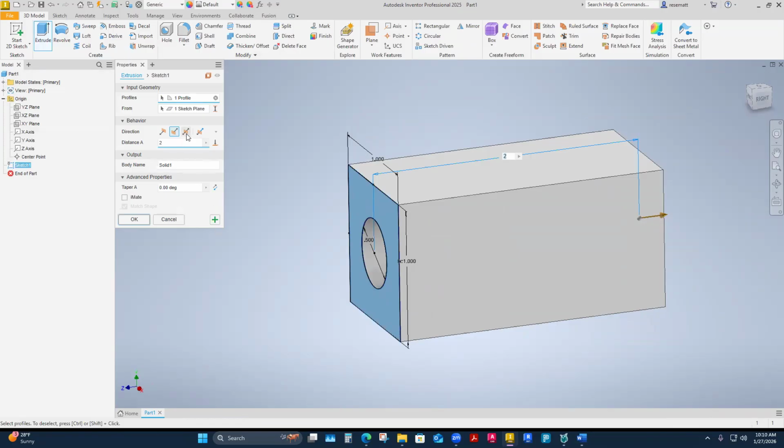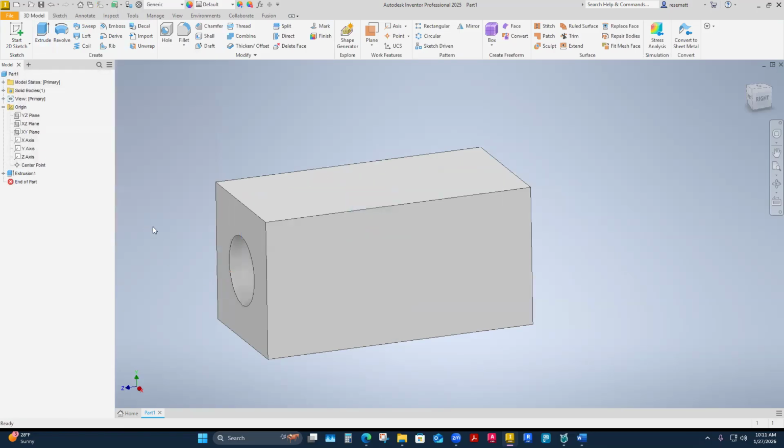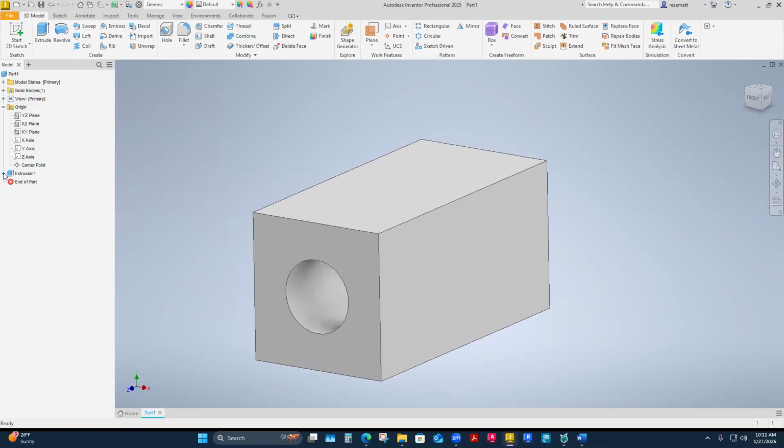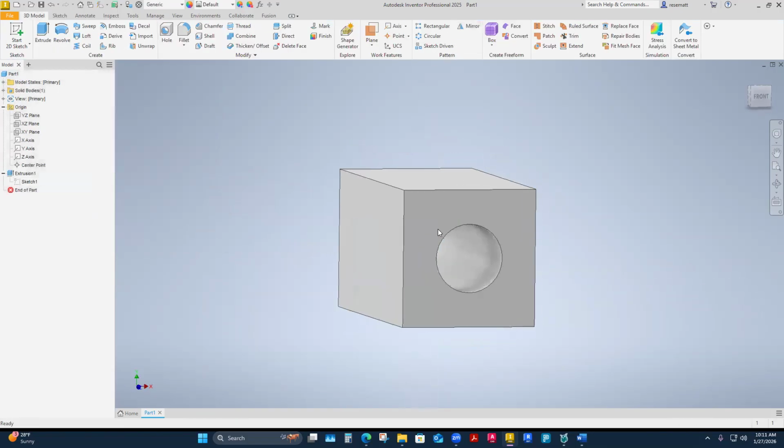But I just showed you why I like this. It's because usually I'm going to use these planes as constraint drivers in my assembly. So I tend to use this more. Maybe I'll just start using it because I tend to use it this way anyway. So I'll start to split it, sketch over center. The only thing that makes it annoying is you have to remember when you go in to edit that sketch, you're going to be in the middle. Sometimes it's going to look like you're in the middle of material, and F7 slice graphics is helpful to slice into where the sketch really is.